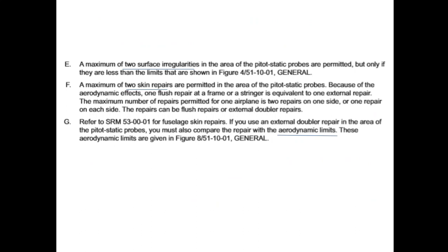And then for the structure strength, you must make sure the aircraft structure is still able to maintain the factor of safety of 1.5 as required by regulation. Any damage will reduce the aircraft factor of safety. If the factor of safety is reduced below 1.5, then the damage is not acceptable and should be repaired, or the part should be replaced. Thank you.